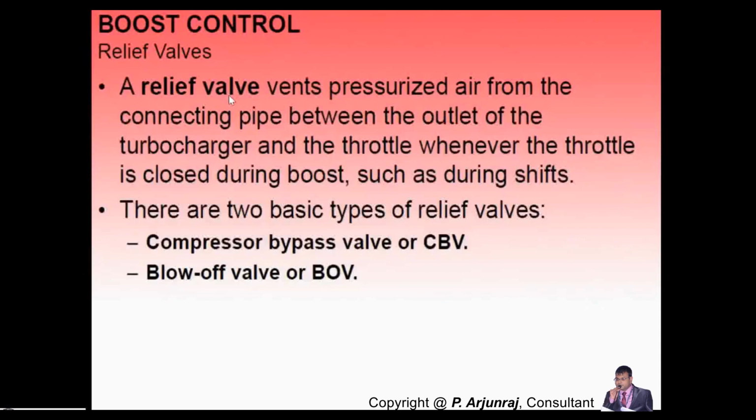Okay? So the function of the valve is basically to open and also to close, depending upon the boost pressure the exhaust gas is going to deliver. When the exhaust gas is coming with high boost pressure, then this will get closed, and this will open when we have the normal boost pressure. Okay, the relief valve vents the pressurized air between the outlet of the turbocharger and the throttle.